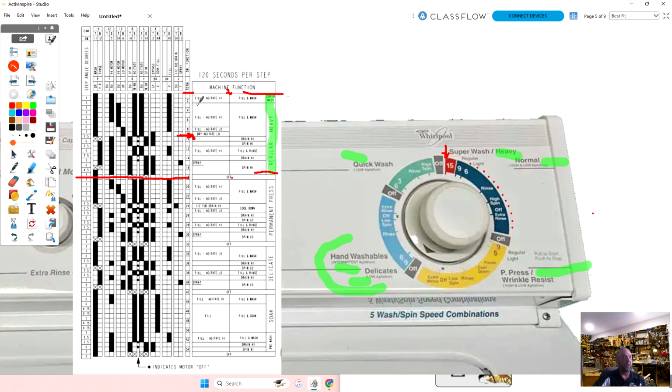Okay, well, I see you all like, well, I don't know. If you look from here to here, it's going to start to drain. What cycle happens at 12? The rinse cycle. Okay? Well, the rinse cycle's right here. So this is the 12th increment in the timer chart, and I'll explain it in a minute. I'm right about here on the 10th increment, just before the rinse starts. So right about here, the machine's going to start draining, and then we'll get into the rinse cycle.